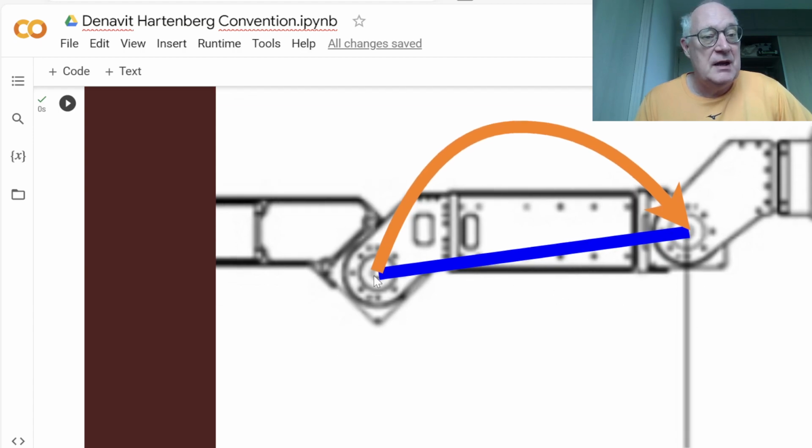The only thing that matters is the displacement from this joint to that joint in a straight line, independently of what the actual link does. And then we can model this rotation here. And of course that also applies to all the further links that are attached. Like the end effector would also rotate around this point.